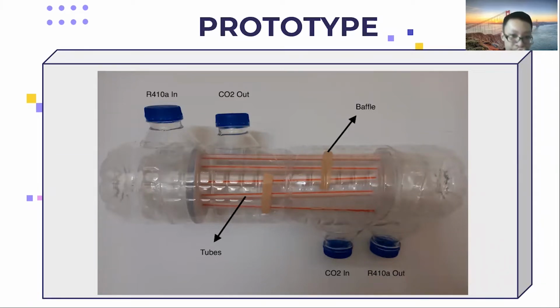However, our group faced a little bit of a problem with the baffle and also the tubes, since the baffle is 2 meters while the tube is 3.6 meters, which means that there isn't much difference. So our solution is to situate it in the center.